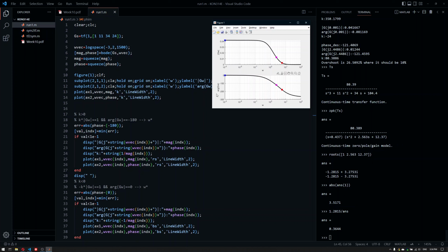But then again, it doesn't really give you the best tools here. Because for this example, you're designing a p-type controller, and you know all this time domain stuff about the p-type controller. You know that the higher the degree of the system, the more difficult it becomes to push all the poles away in order to get the zeta and omega n values for the given settling time and overshoot, etc.